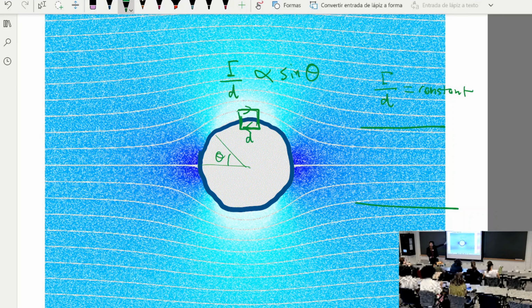So we're going to use the same principle on the airfoils. Once we relate the shape to the circulation, we're going to relate circulation to the speed just outside of the airfoil. And from the speed just outside of the airfoil, we use Bernoulli's to get the pressure just outside of the airfoil. And from pressure, what can we do?